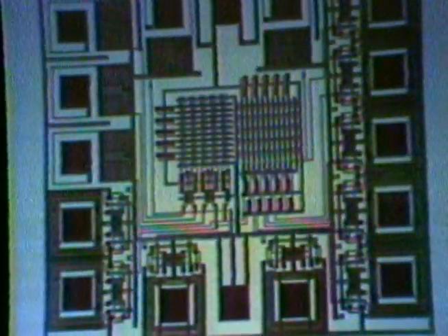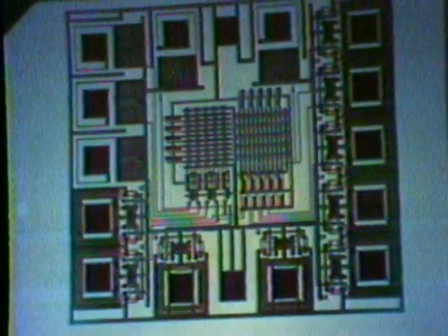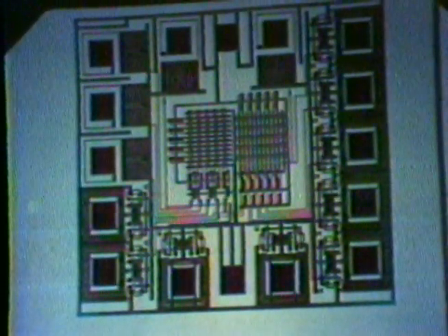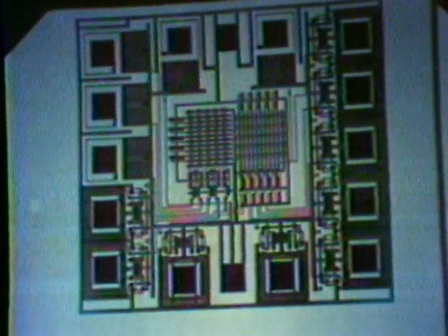That was a traffic light controller that was developed as an example in Mead and Conway's book. And since it was in there and already programmed, I decided to go ahead and lay it out. And this is, in fact, one of the projects that we implemented on the last summer's multi-project chip. And it is the smallest project that has pads around it. And that's because in making a ring of pads, you can't very well get a hole in the middle any smaller than that. In fact, the PLA consumes about 10% of the total area of this project. So you can see it's fairly compact.